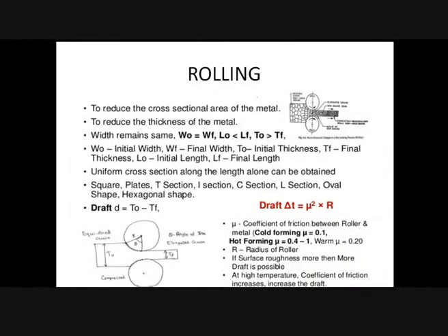They might ask you this question: in the deformation zone, what happens to pressure? Is it increasing, decreasing, increasing and then decreasing, or decreasing and then increasing? The answer is increasing and then decreasing. In the lagging zone, the pressure is only increasing, while in the leading zone, the pressure is always reducing. This is regarding pressure.